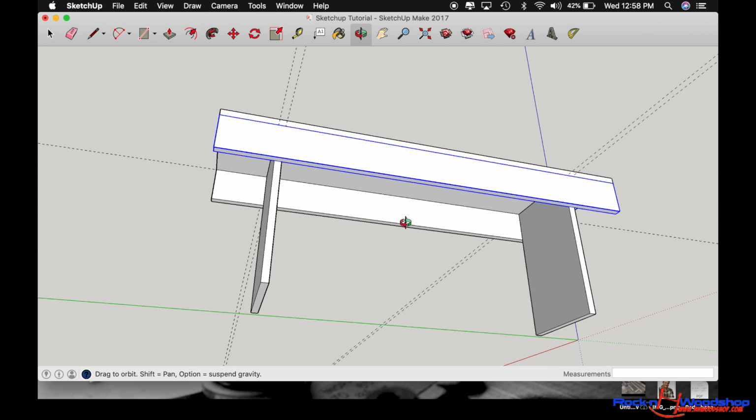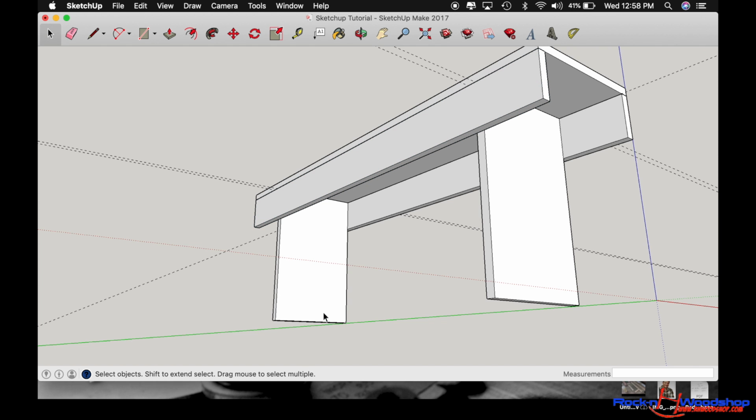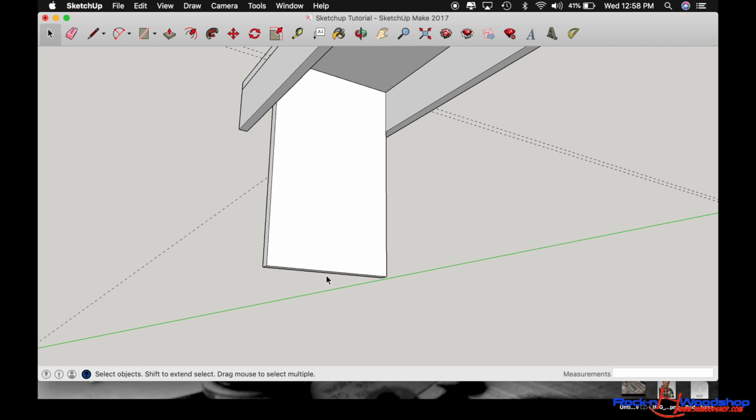Now let's go ahead and add a shelf. Now we're going to get into position with our orbit tool again. And I want to make a shelf 6 inches up. So let's make a reference line with our tape measure, 6 inches up. And we can do a 3/4 inch thick reference line there. And like I said, you're just typing this stuff in as you're dragging. Very simple.